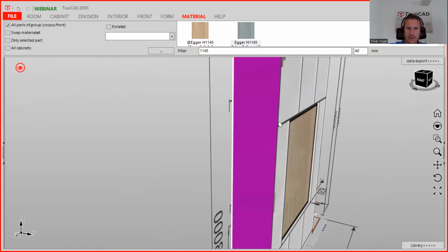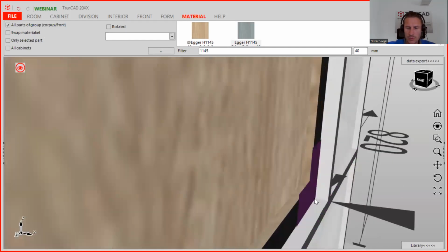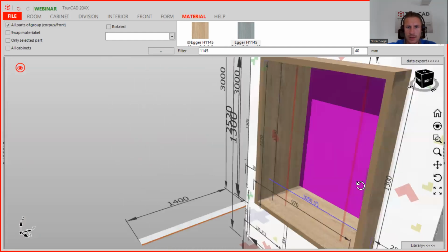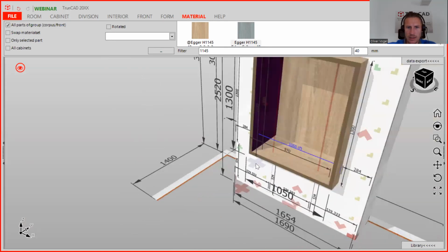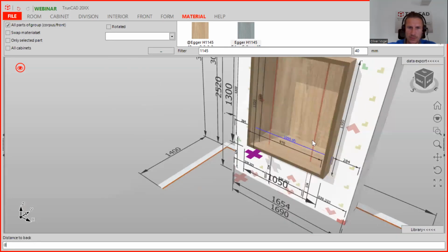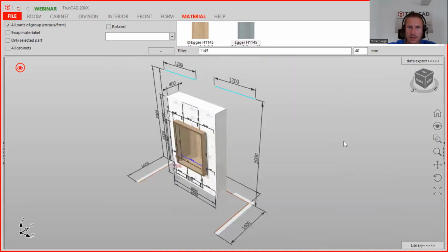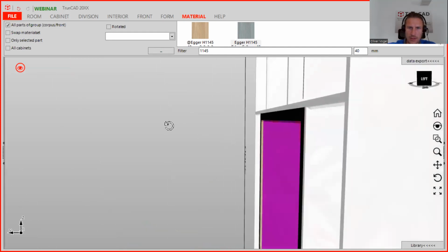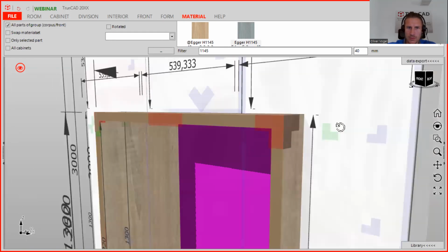So it looks like this. And here we need to change the distance, because the program still sets the second cabinet, the insert, calculating the distance to the back. But because we don't have a back, we click here again on distance to back, and here we set it to 0. And now you see this cabinet is also going to the back.